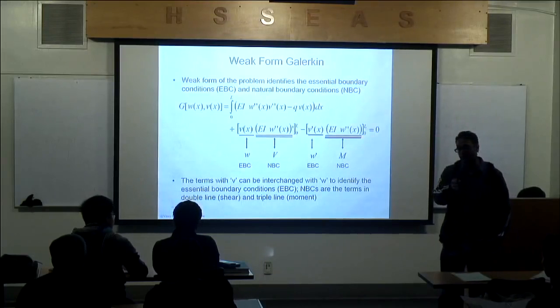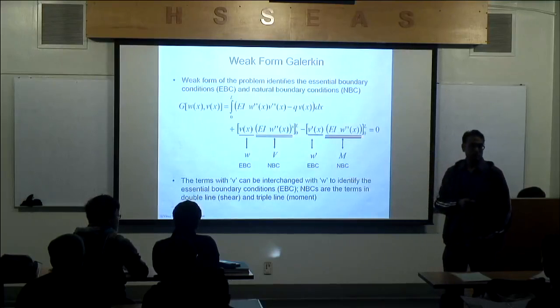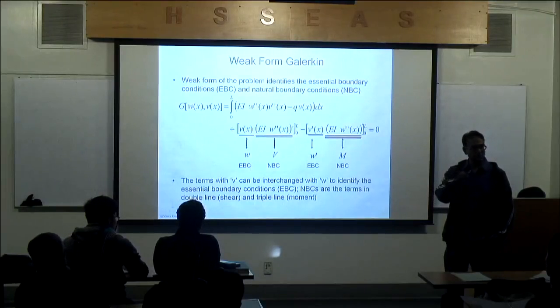So the approximation function, if it's second order, what's going to happen is, since it's Euler-Bernoulli beam theory, can somebody tell me, does the cross-section stay perpendicular to the neutral axis? Yes. Right? We talked about that. So the transverse shear is 0. The transverse shear stress is 0. And so if you use a quadratic polynomial, you have inconsistency. You'll get 0 shear. Okay?